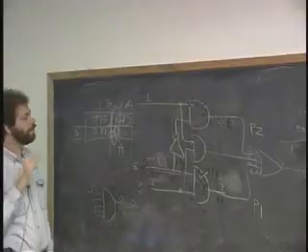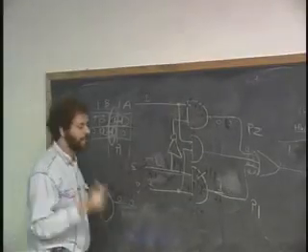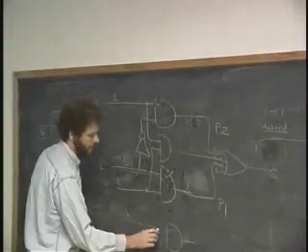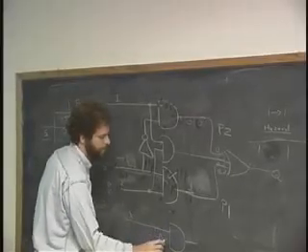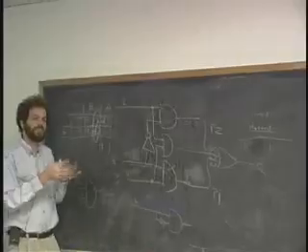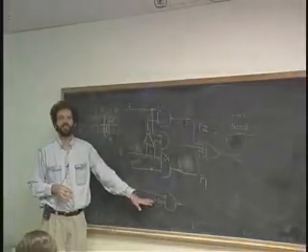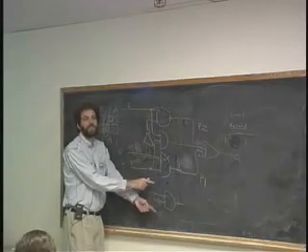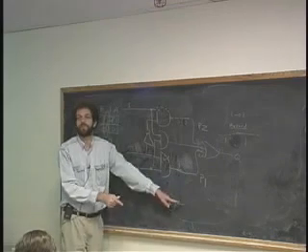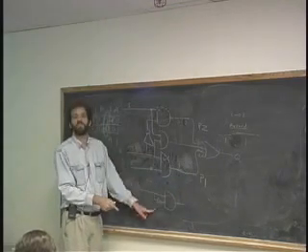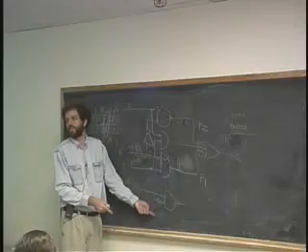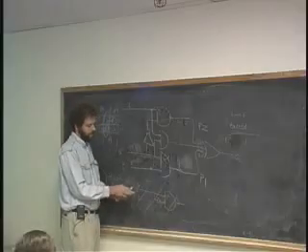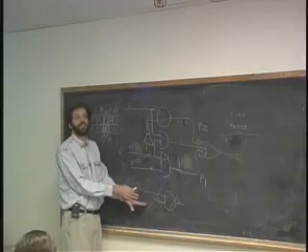It turns out that there is one degenerate case, which doesn't matter, which is if I have an AND gate and I have an input, let's call it X, and I feed it both X and X bar at the same time. According to the definition of sum of products, this is legal to do. In this case, we have a single input change, which would result in a double input change to the AND gate, which could result in a glitch on the output. However, would you ever want to do this? Does it ever make sense to put A and A bar? No. So this might generate a glitch. Technically, it is sum of products, but there'd be never a reason to do it.